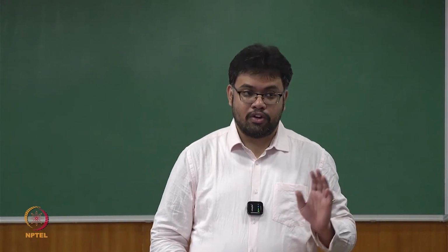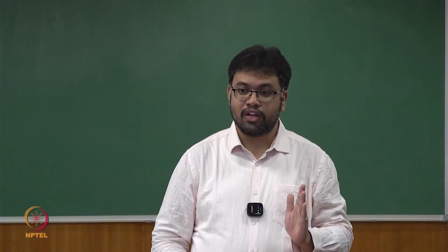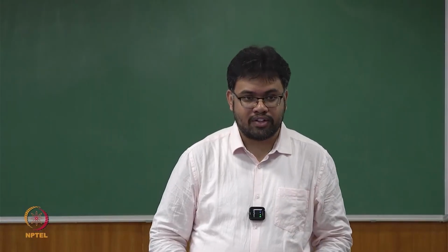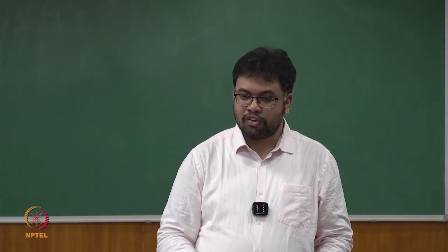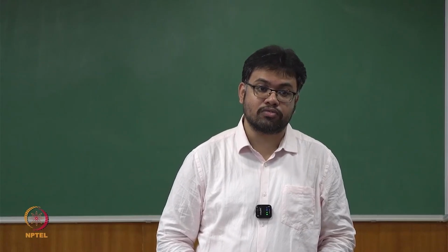Okay, don't get confused with that 90%, 95% clause of the Indian code. That is not the modal participation factor, because once you solve, you may find some cases where the modal participation factor could be negative also.